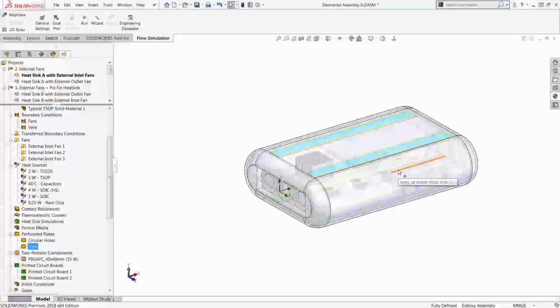Now what does this mean? So first off, the holes and the slots are going to add some resistance for the air to escape from these 2 areas. If I actually modeled all the holes in there, it would be computationally very expensive to actually mesh them and run them, which would mean my time exponentially increases. But from a flow simulation perspective, I just want to simulate the effects of those.